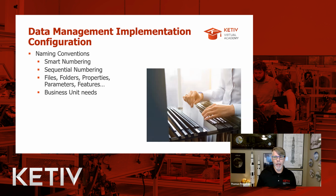What about sequential numbering? There are a lot of companies out there that are not so dependent upon the name so much as they're concerned about reducing redundancy and duplication. So having a uniquely identifiable number in a sequential type of pattern is more important to them than understanding, by looking at its file name, what this file is all about. There are other things that we can rely upon, like properties and attributes, that can provide some of that characteristic information that we need, as opposed to relying upon a smart part numbering system to provide that, okay?